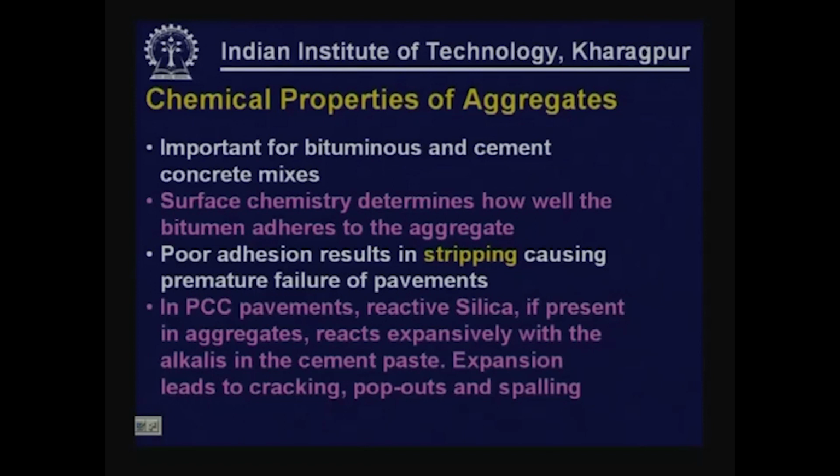When it is present in aggregates, it reacts expansively with the alkalis in the cement paste. Expansion, which is an increase in volume, leads to cracking, pop outs and spoiling of concrete.